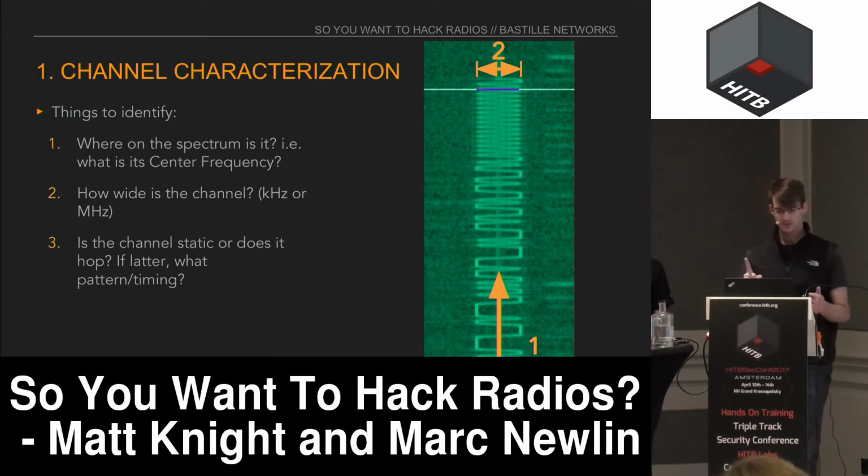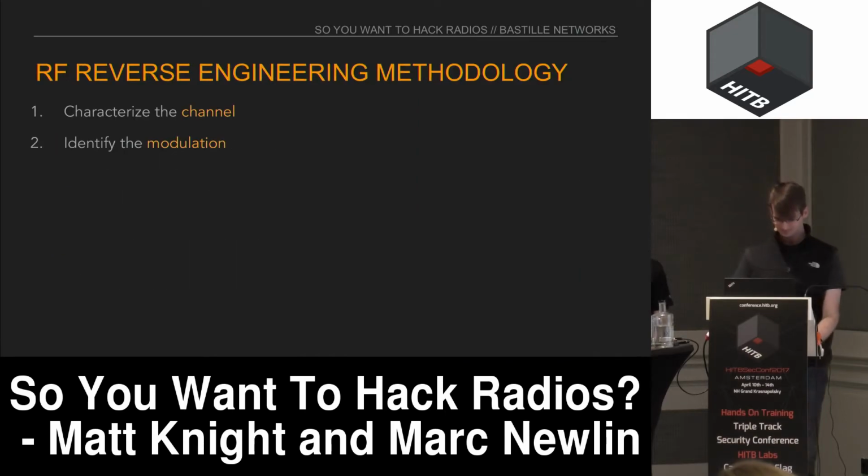We're looking for what is its center frequency, what is the middle of the channel. We're looking to establish how wide the channel is, how much spectrum does the signal traverse. And finally, we're looking to establish whether or not it's a static channel or whether there are multiple channels and the signal hops around. So those are really the 3 things that come to defining the channel.